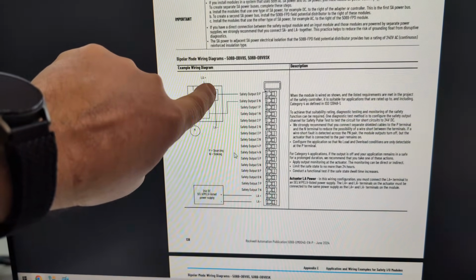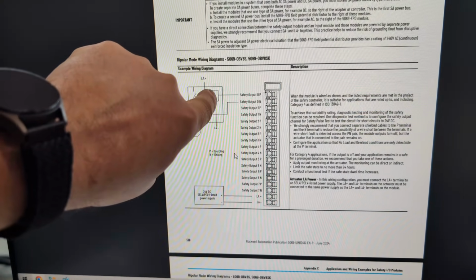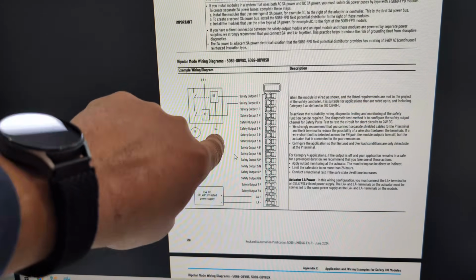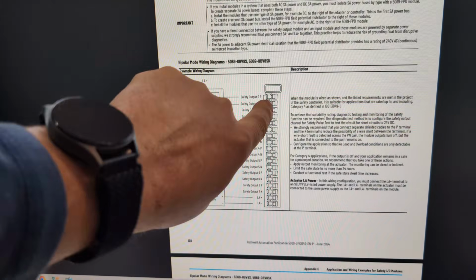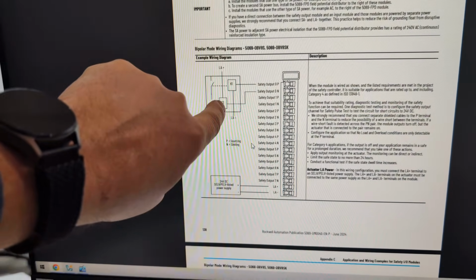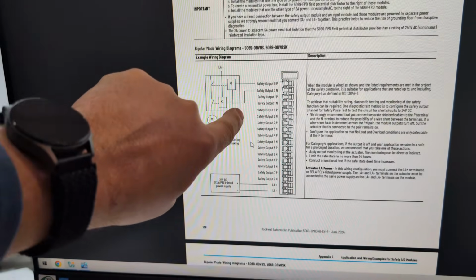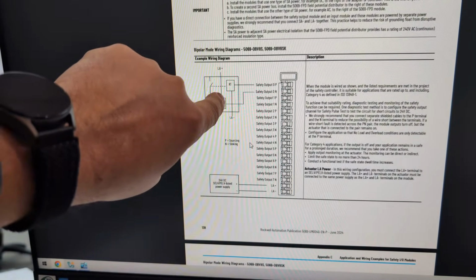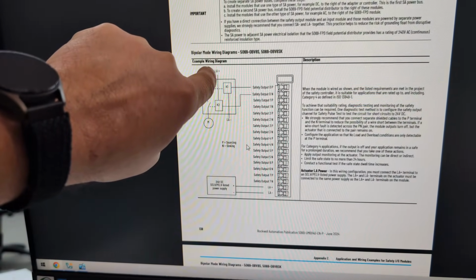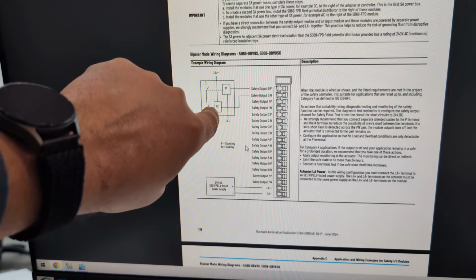And so we got one wire going to K1, and on that one, we're going to go to the minus of our power supply. The other one, we're actually going to the plus, and that gives us that diversity. But this one right here is twitching, like it's getting some AC feedback. That instinct would be that it probably needs some type of diode on it, but I would love, well, it has a diode on it. I have no idea why that thing's flashing. Anybody got any thoughts on that?